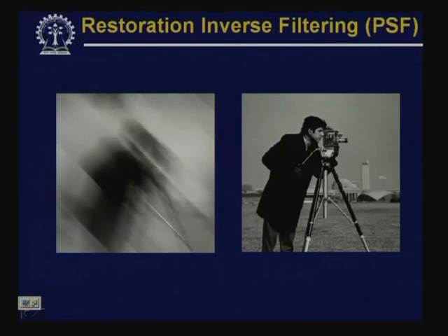But again, with this inverse filtering approach, the major problem is, as we said, that we have to consider the (u,v) values for reconstruction within a limited domain. Now, how do we say up to what extent of (u,v) value we should go? That is again image dependent. So, it is not very easy to decide to what extent of frequency components we should consider for the reconstruction of the original image if I go for direct inverse filtering.